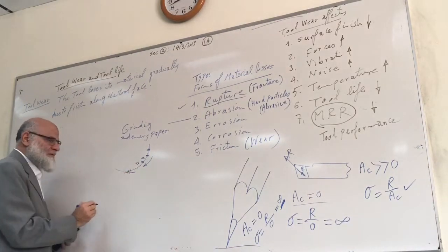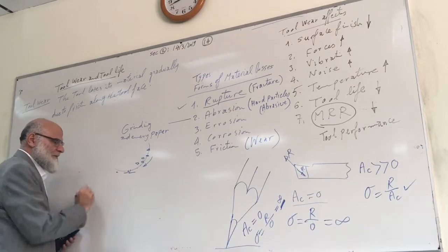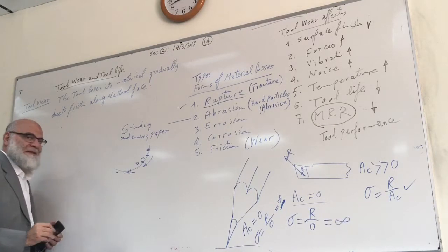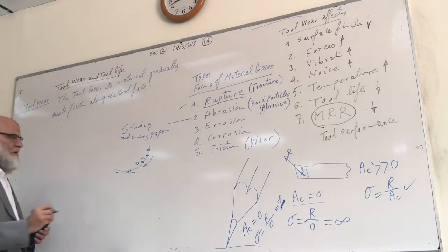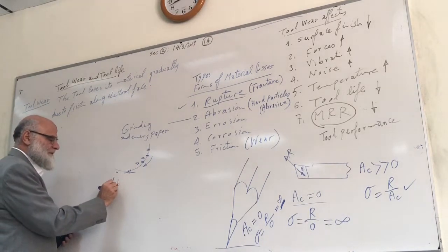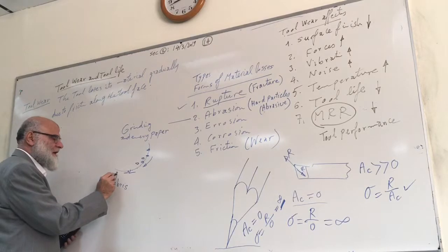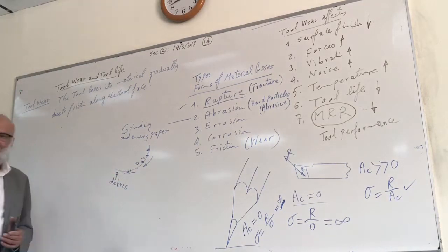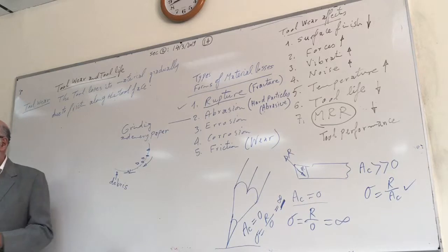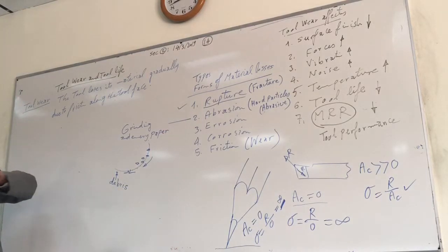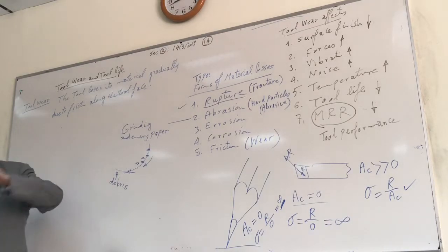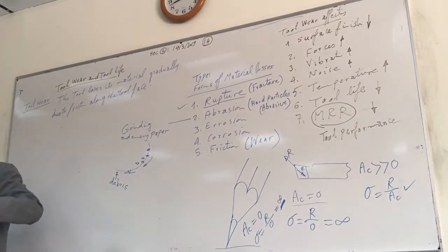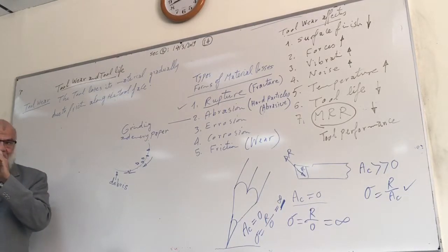It is very small, the same as a chip, but it's called debris. Debris are very fine chips going out of grinding. Because of its very small size, the heat given to this small size will raise the temperature to red temperature. Therefore, you see the debris going out red, the spark. Spark is not an electrical spark, it is a mechanical spark.